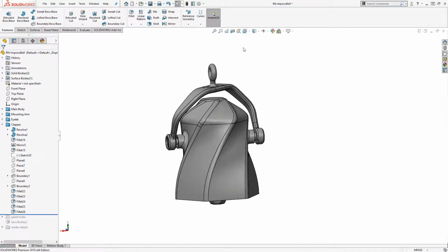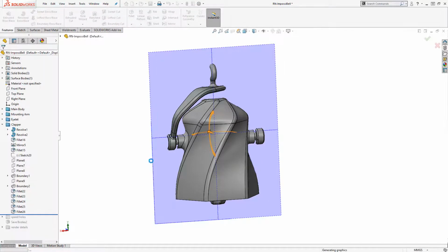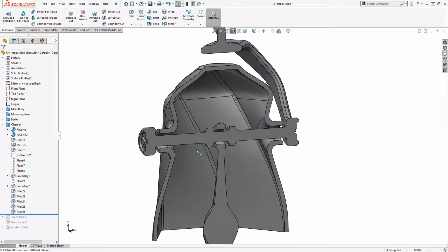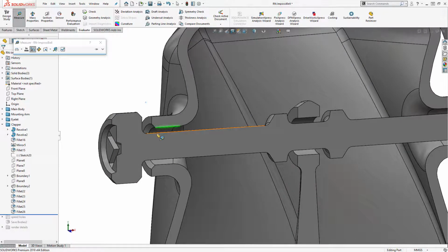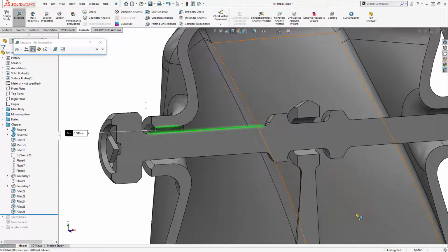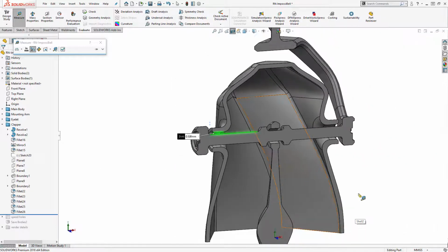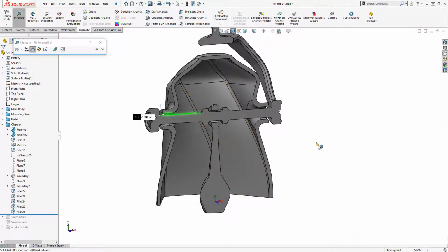By the way, as far as clearances go, we can investigate that here. I honestly can't remember exactly what I used for clearance. It's about 0.5 millimeter of clearance. This printing process does use powder and a resin, so there was the need to blast out with compressed air any residual powder in there. So that's the main reason behind that 0.5 millimeter of clearance.